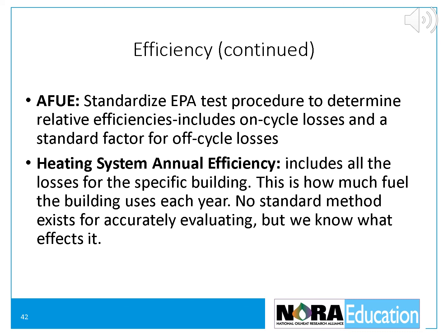This brings us to heating system annual efficiency. This is the actual true efficiency of the whole system over the heating season. It is the difference between the number of BTUs the consumer bought and the number of BTUs they used to heat the building and domestic hot water. It involves all of the energy losses and system interactions measured over the course of a whole year. It is a function of the gallons of oil used, the temperature of the outside air, solar gain, exposure to wind, the temperature inside the building, the number of occupants and their lifestyle, as well as the amount and temperature of the domestic hot water they used.